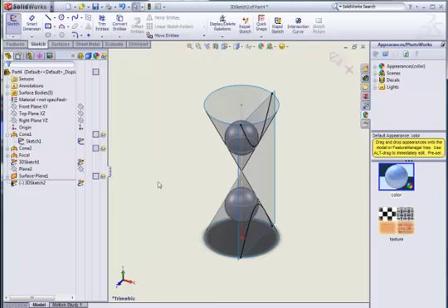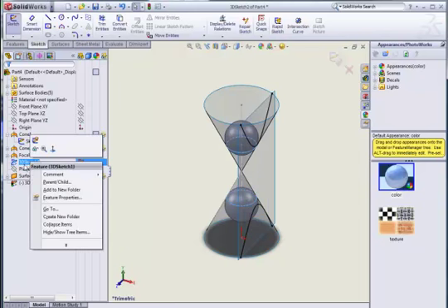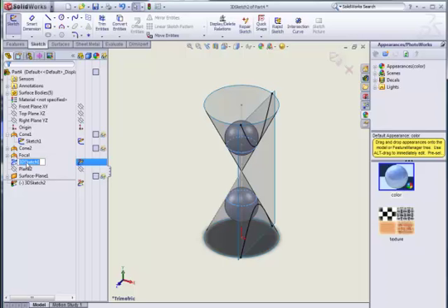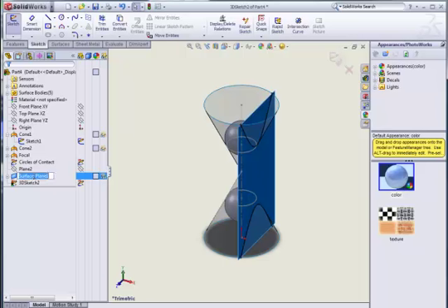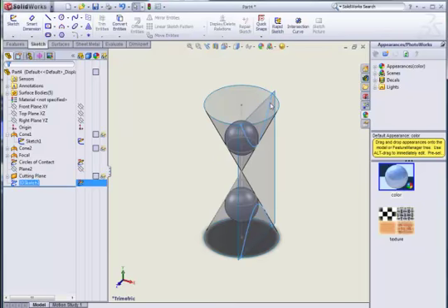So now we can rename our sketches. So we'll rename our first 3D sketch, press F2, call it circles of contact. And rename our planar surface as cutting plane. And once we exit the sketch, we can rename our 3D sketch as our hyperbolae.